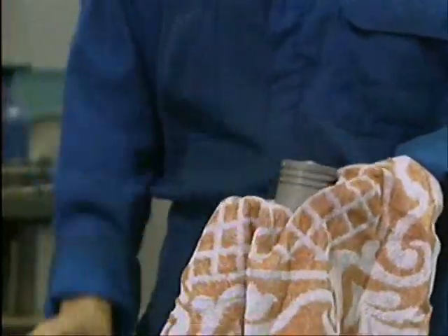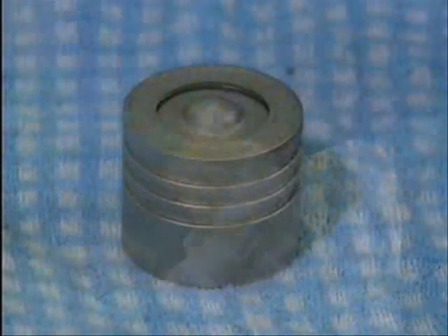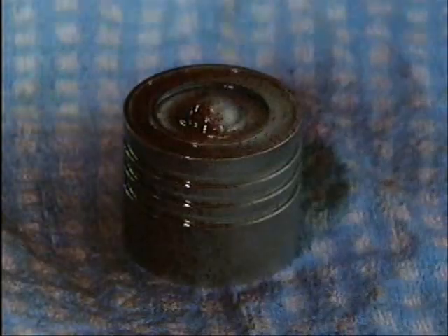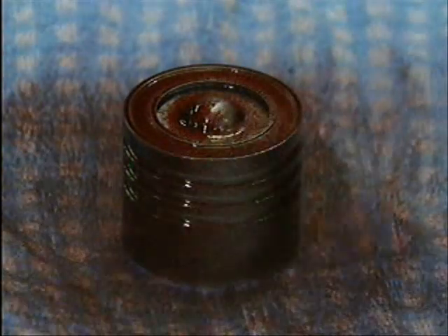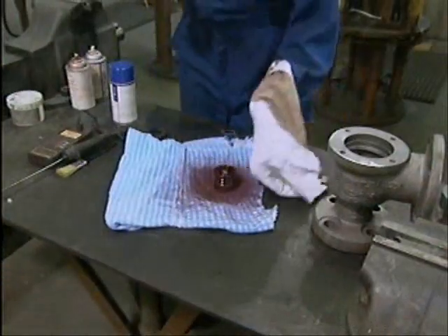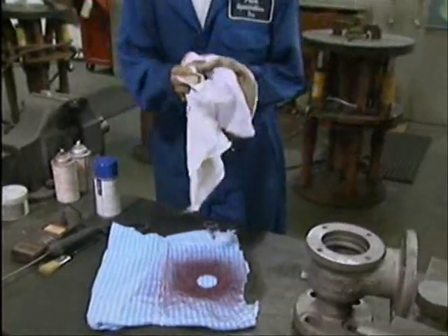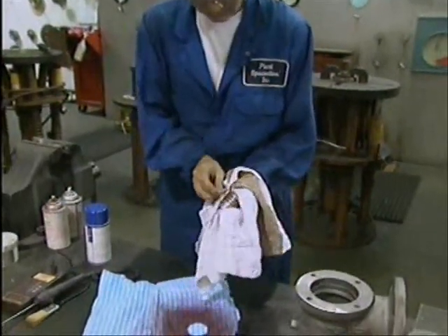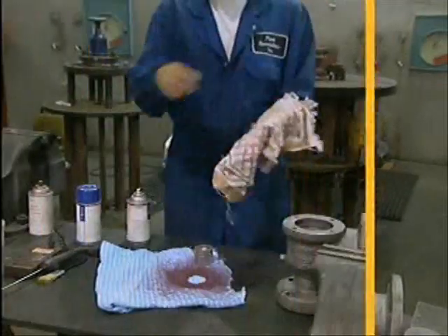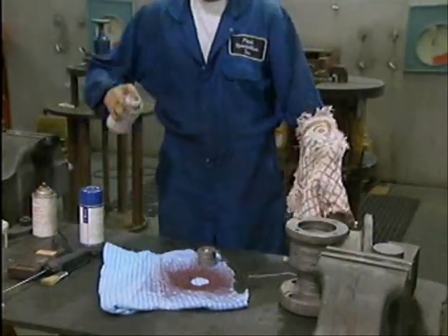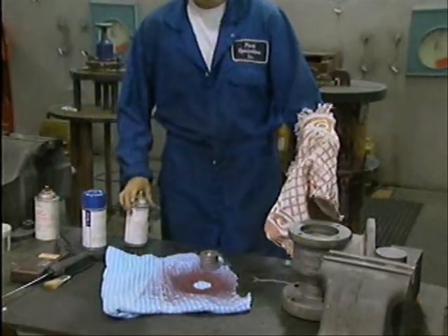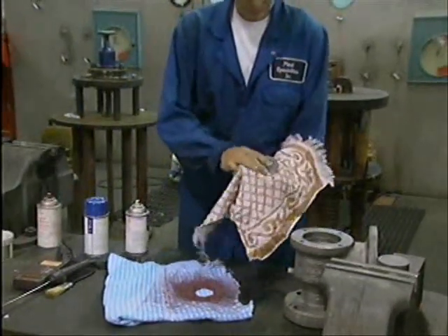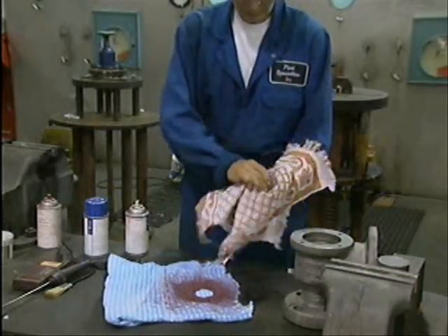To do this, first clean the disc. Then apply the dye penetrant oil, which is a mixture of light penetrating oil and dye. After allowing time for the dye-penetrant oil to be drawn into surface cracks, wipe the excess oil off with a clean cloth. Then apply a light mist of a dye-penetrant surface cleaner on a cloth, and use this cloth to clean off the disc. Only the dye and the cracks will remain.